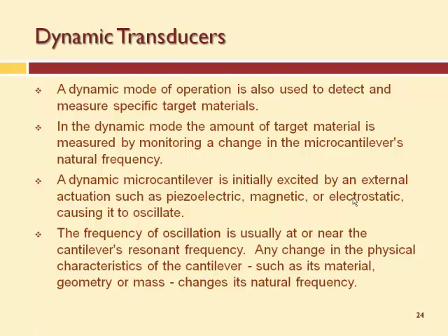So you can get your cantilever to vibrate at its resonant frequency by changing the frequency that you're exciting it with. Once it matches, you'll see the maximum motion. And we'll do that. We could go break a cantilever today. You guys like breaking stuff.